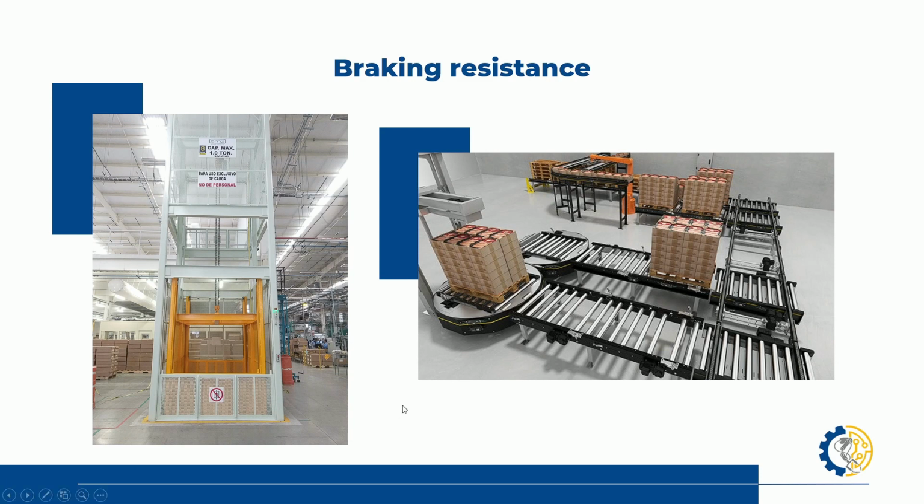And today we're going to be reviewing and analyzing our brake resistance. Now, I had previously told you that this type of resistance is very popular in some applications. What type of applications, you might ask? Motion applications, vertical motion or vertical movement applications like cranes, freight elevators, etc. Applications in which the inertia is too large for the load to stop on its own.